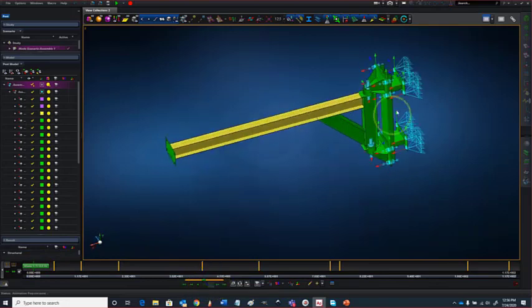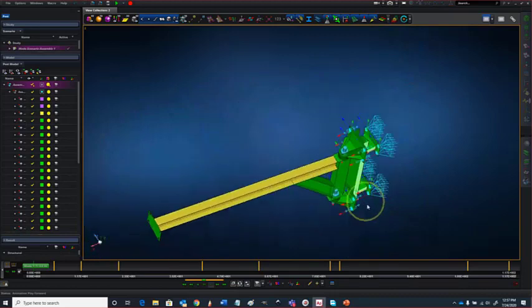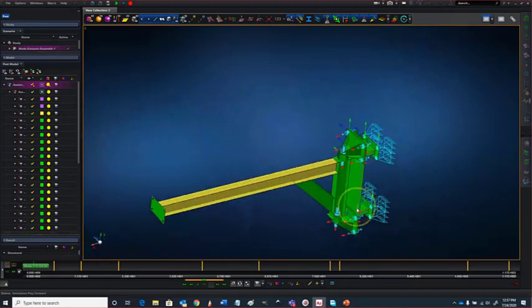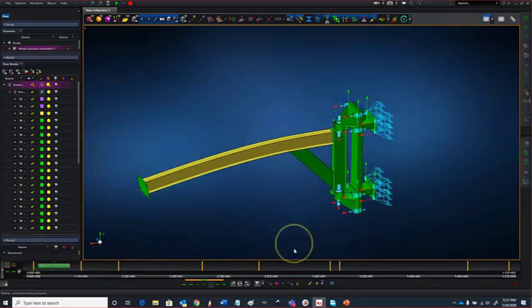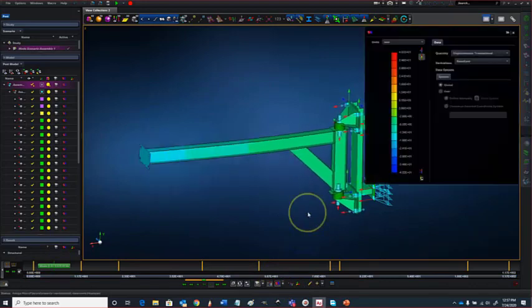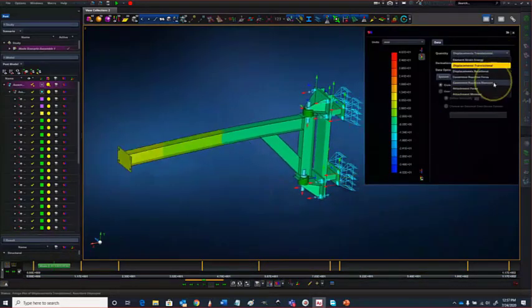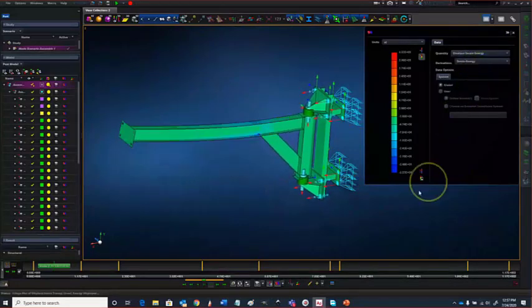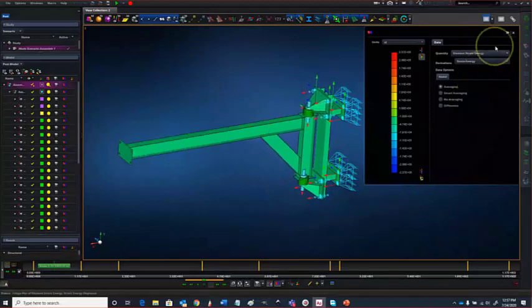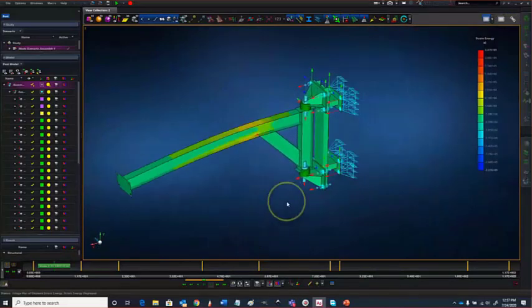And now we can see that the joints were indeed applied correctly, and we shouldn't have any load transfer in that direction. But while we're at it, we can jump to the different modes, maybe plot some arbitrary fringes, maybe use the strain energy option to get some nice stress plots.